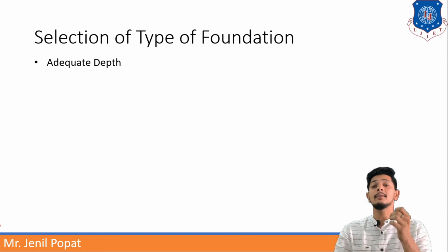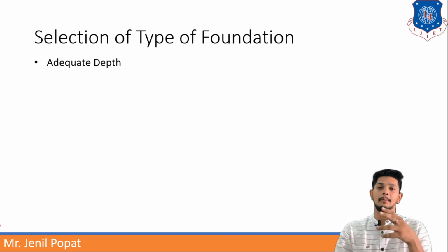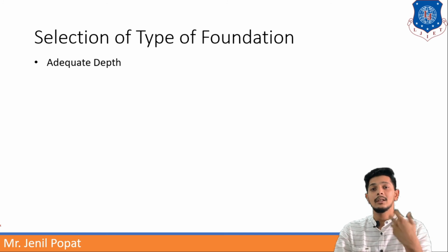I mean, if the soil bearing capacity is lesser, you need more depth of the foundation. Same way, if the soil bearing capacity is available and more at shallow depth, you need lesser depth. So this is how you decide its perfect depth.